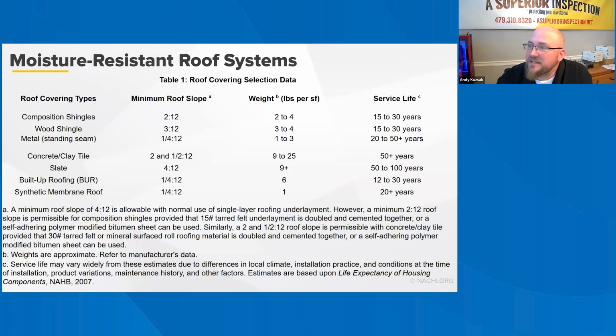Shows a double underlayment detail to be used on slopes of less than 4:12 for these two types of roof coverings. For roof slopes between 2:12, 2 units vertical and 12 units horizontal, which equals a 9.5 degree slope, to 4:12, which is 4 units vertical and 12 units horizontal, which equals an 18.5 degree slope, underlayment should be 2 layers applied in the following manner.